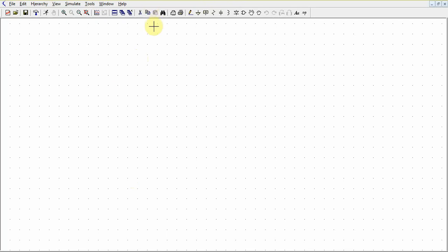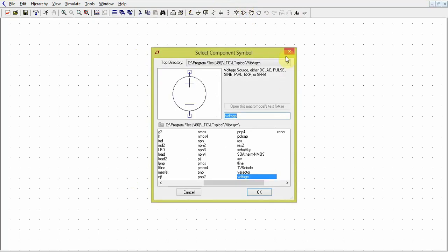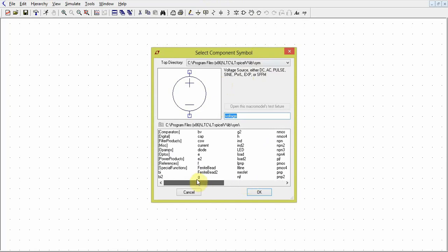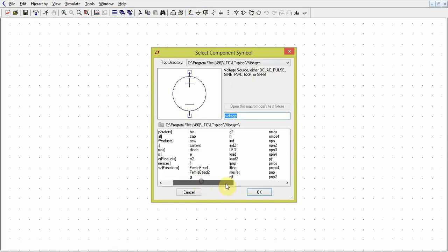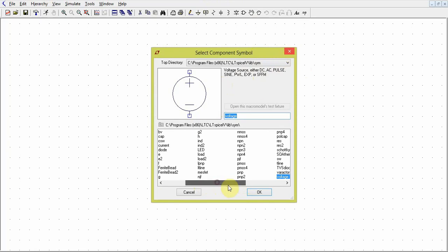For example, of course, you could always click on these buttons here to do your thing. This one is to add part, for example, or you just press F2. I just use the keys because they're all right next to each other, and yeah, I've just gotten used to doing that, just pressing keys. So of course, suppose you want to insert really basic components like resistors and capacitors.